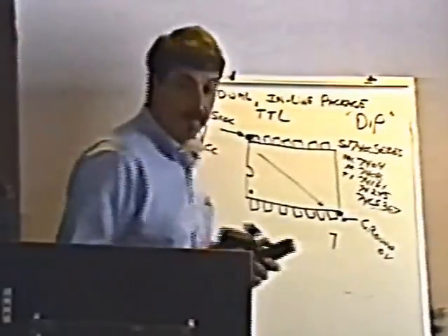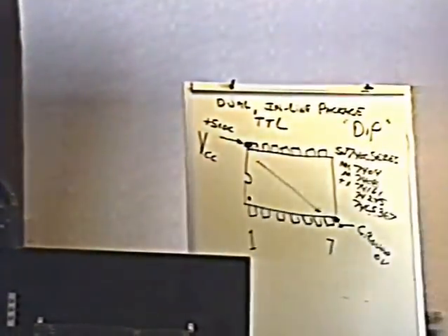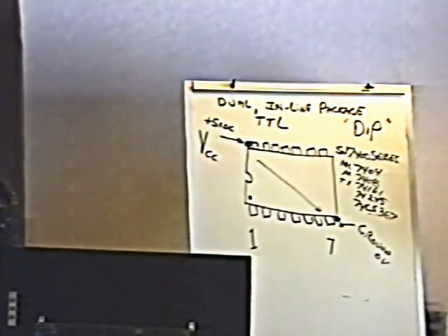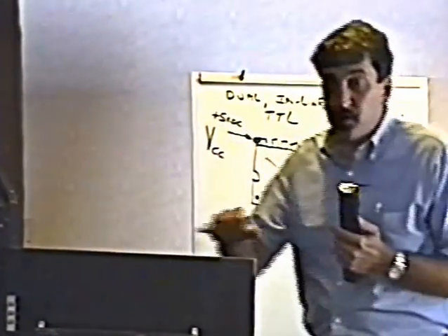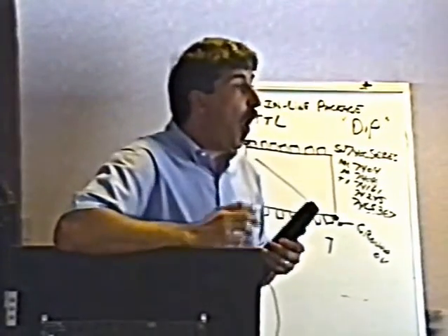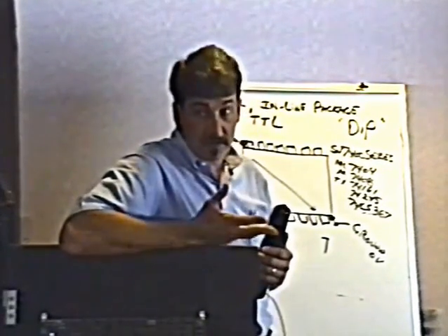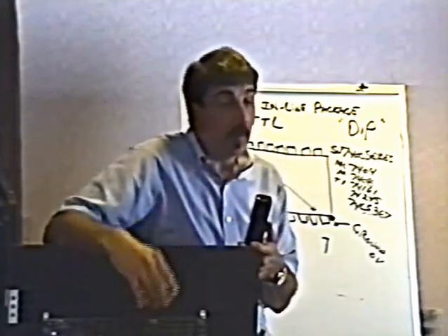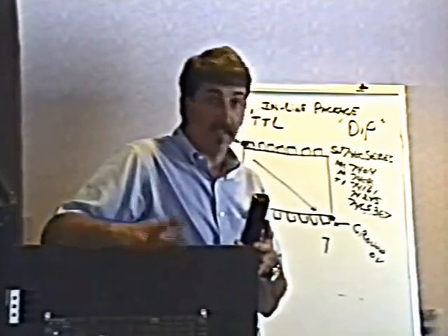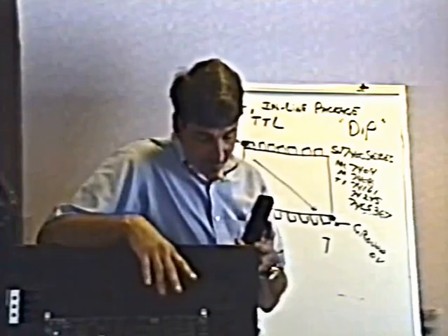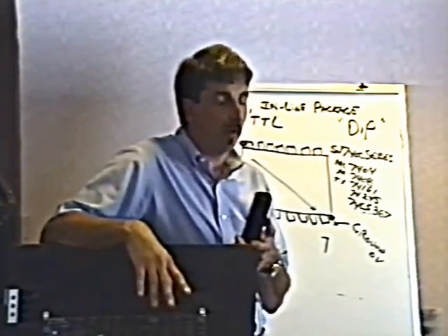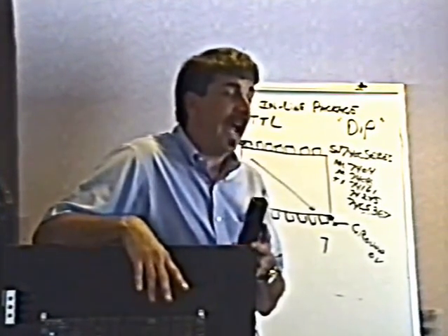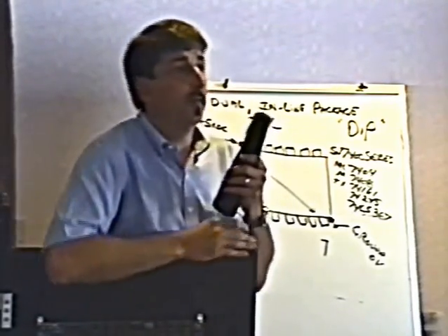Okay, so this is what I'm referring to. When I refer to garbage on the screen, this is the kind of thing that I'm talking about. Naturally, you always want to eliminate your power supply as a cause of this problem. You want to make sure that you adjust the 5 volts so that all that is perfect before you do anything to the board.